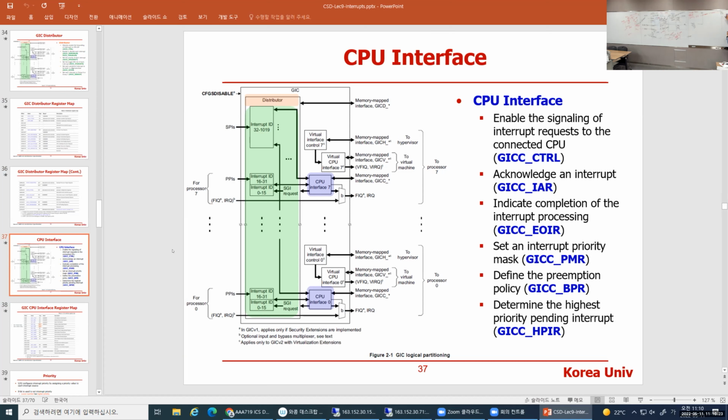Interrupt happens. Then the goal is I want to execute one of these four actual interrupt service routines. That is the goal. Assuming that there are only four interrupts. In ISR, according to the protocol, right? Interrupt is generated. You are supposed to refer to the interrupt vector table. So there are 8 vectors, right? Branch, reset, branch, something, right? So based on that interrupt vector table, you are jumping to ISR, interrupt service routine. Not that interrupt service routine, but the central interrupt service routine, not the individual interrupt service routine.